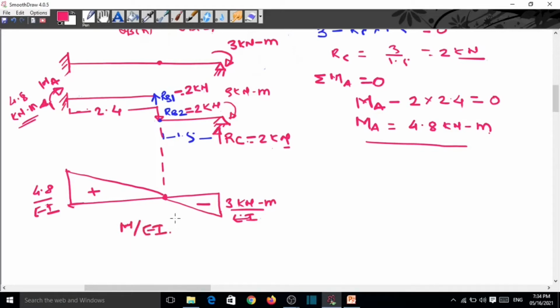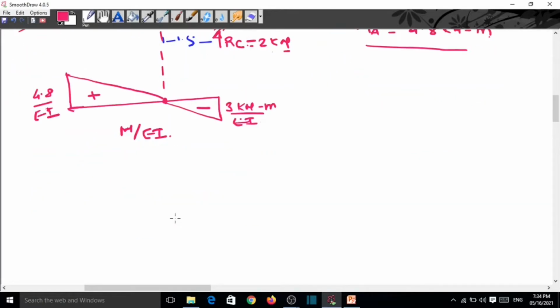The next is the point load. So now we draw the free body diagram for this point load. This is a hinge and here is a hinge. Eight kilonewton. This is 1.2 and this is 1.2. Now this is a reaction because this is a downward load, so with the upward reaction, this is RB1 suppose. So it is upward, and here is the downward force.